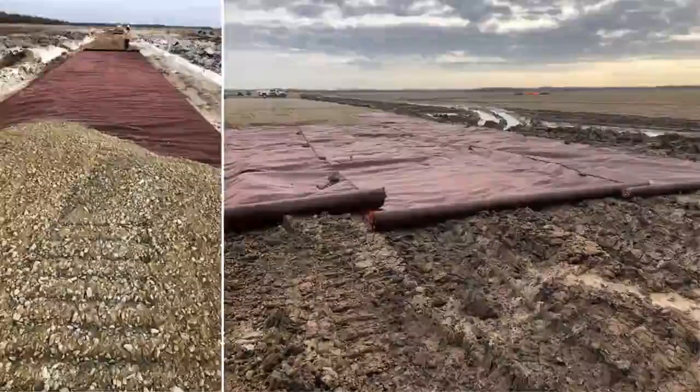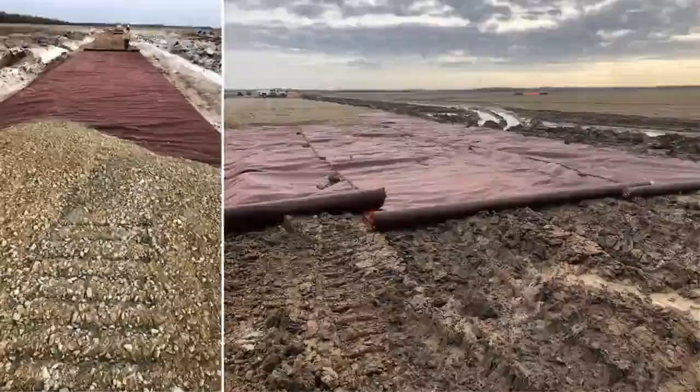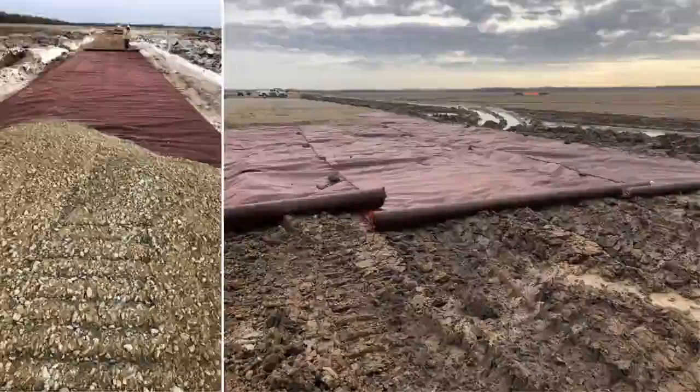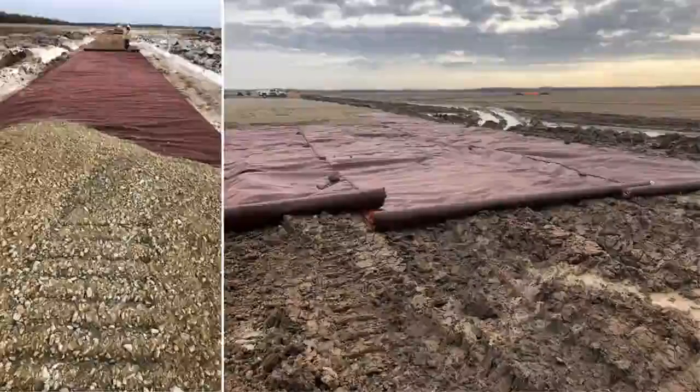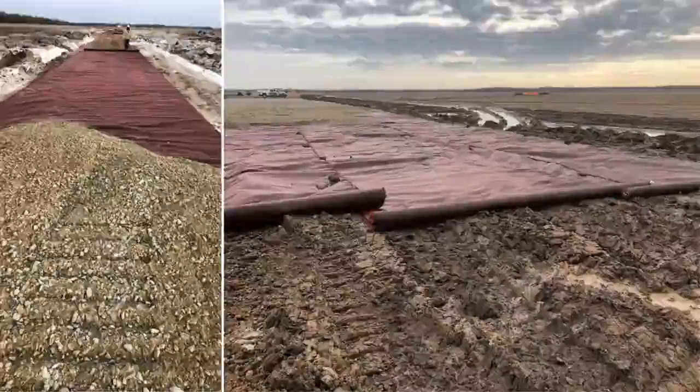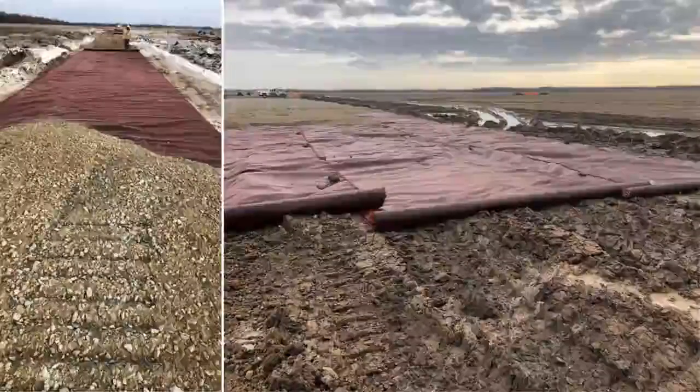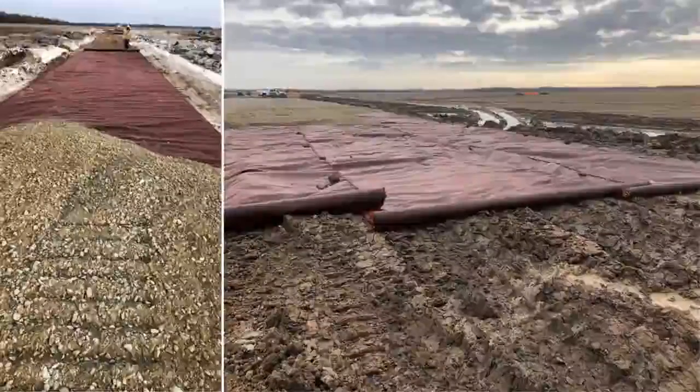We achieve continuity when the road is wider than the roll width by overlapping adjacent rolls of fabric. And then on this project, some additional thickness was brought in so that that 7-inch structural aggregate always remained intact despite additional road usage by the piling rigs.